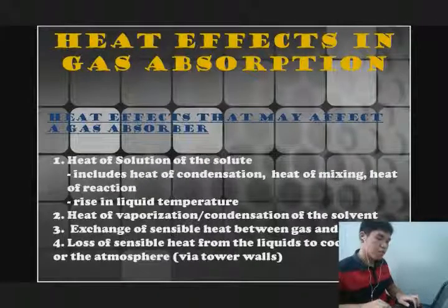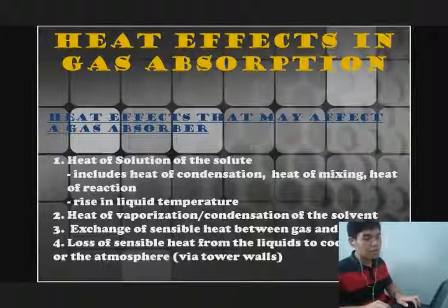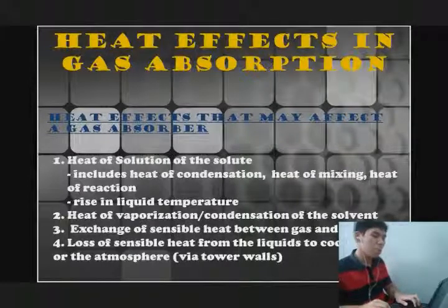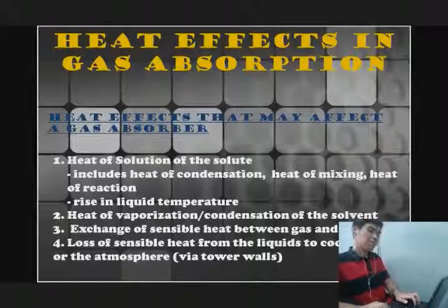One is the heat of solution of the solute. It involves the heat liberated in mixing, heat liberated in condensation, as well as heat liberated in reaction. Others include the heat of vaporization or condensation of the solvent, temperature difference that may result in heat transfer between the solute and the solvent, and loss of heat to the surroundings.